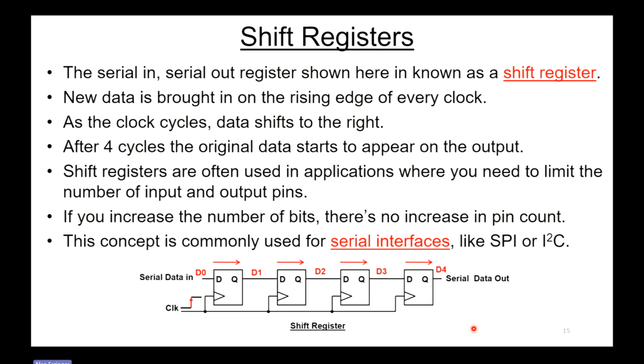Shift registers, serial in, serial out register shown here is known as a shift register. New data is brought in on the rising edge of every clock. And as the clock cycles, data gets shifted to the right, one position every time a clock edge comes through.